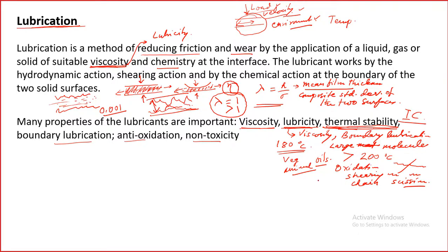As well as we have other varieties, mineral oils and synthetic oils. So mineral oils are less thermally stable compared to synthetic oils. Synthetic oils are the best in terms of thermal stability. So this is how we have to think about lubricant selection for our tribological application.